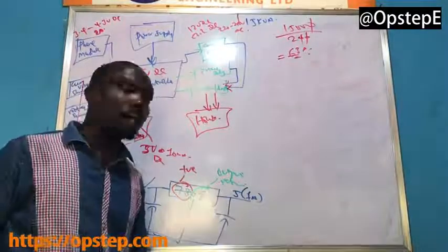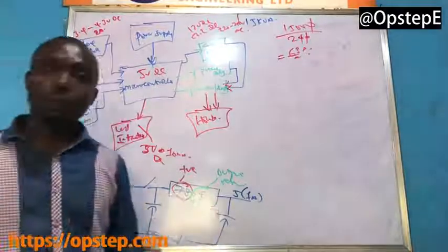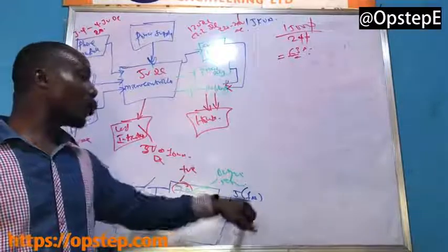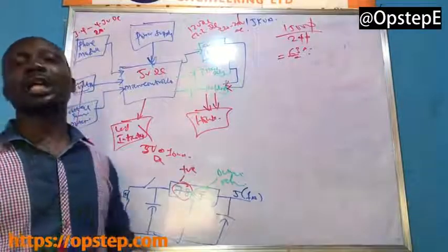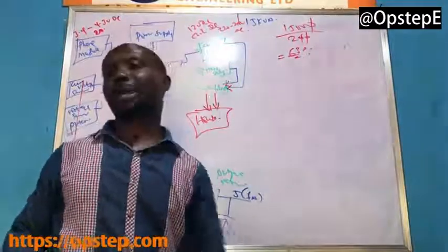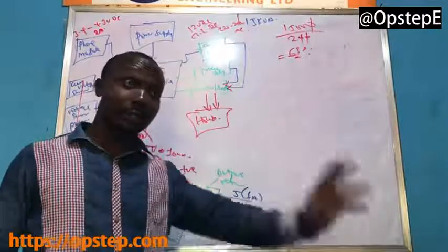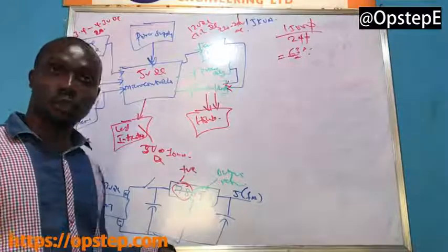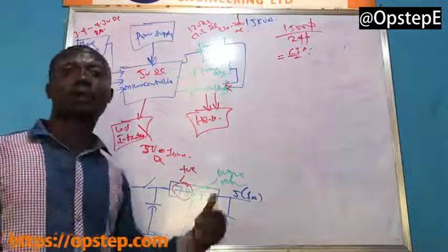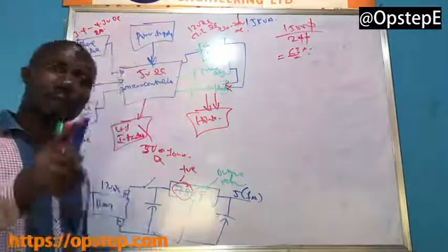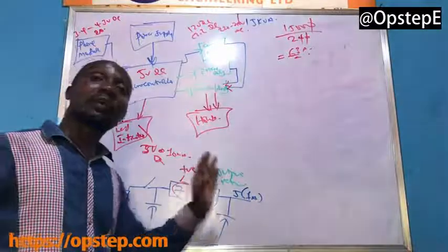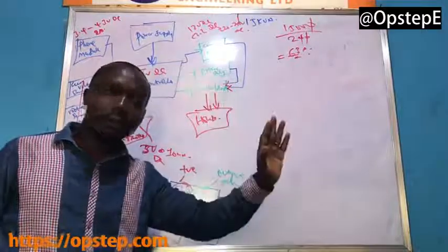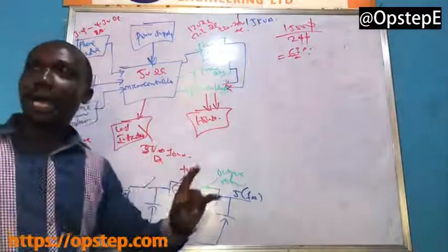It shuts down. It also has overload protection, which means that if you bring in a load at the output that is requesting more than the 1 amp that it can give, or say more than the 1.5 amps that some versions can deliver, it will just shut down instead of getting damaged. Do you get it? So I told you before that it offers you some very good benefits. Part of those benefits is that you have a regulated output voltage that does not change at 1 amp, typical, and then it has thermal shutdown and overload protection.